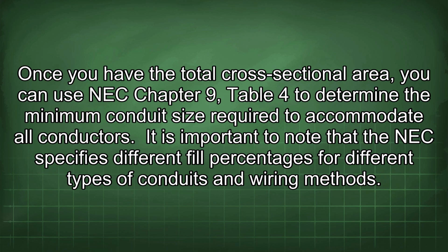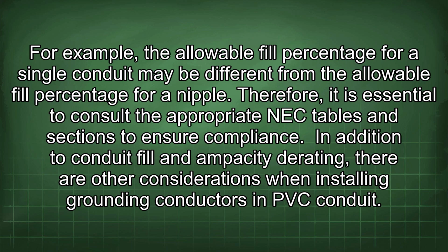It is important to note that the NEC specifies different fill percentages for different types of conduits and wiring methods. For example, the allowable fill percentage for a single conduit may be different from the allowable fill percentage for a nipple. Therefore, it is essential to consult the appropriate NEC tables and sections to ensure compliance.